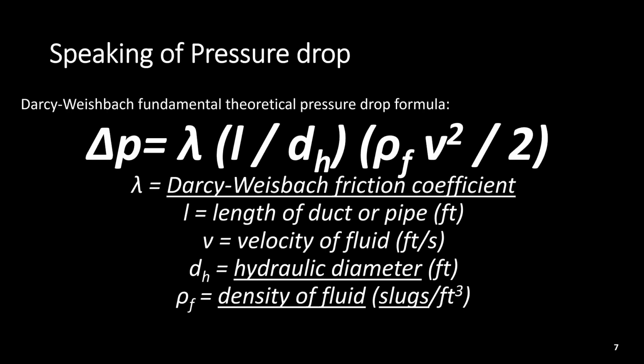Speaking of pressure drop, here's an equation. It's a very theoretical equation based on fundamental energy calculations, the Darcy-Weisbach formula, and it's got all sorts of interesting stuff in there: a friction coefficient, the length of the pipe, the velocity of the fluid, the hydraulic diameter in feet, the density of the fluid in slugs per cubic feet. When's the last time you had to deal with a slug? And I don't mean one of your coworkers.